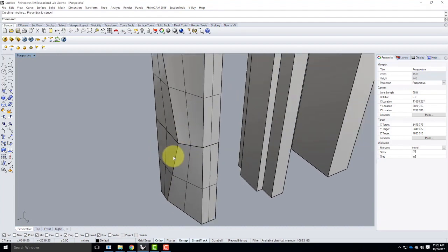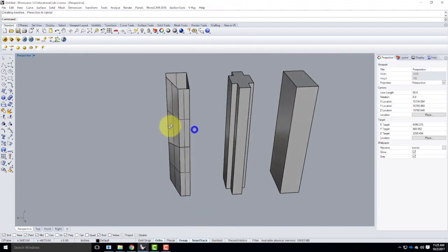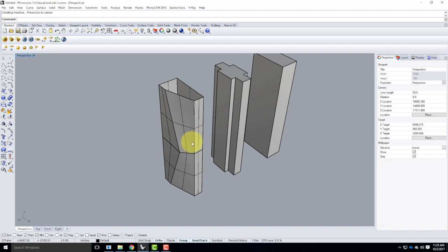So in this case, because I'm doing lofts, all of these surfaces are what is called developable surfaces, which means that you can create them out of a flat sheet. It's just a matter of twisting the sheet to create the end result. It's not a bulging surface. It's not an orange. If I had an orange and I wanted to lay it flat, I would have to break apart the peel of the orange to lay that peel flat.